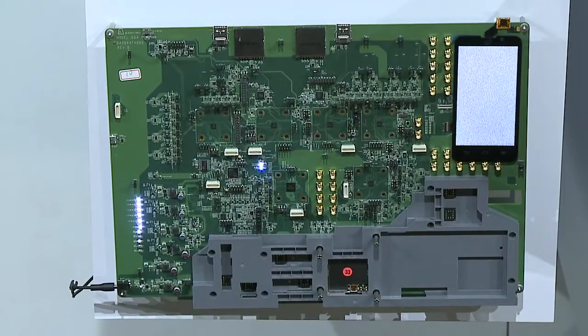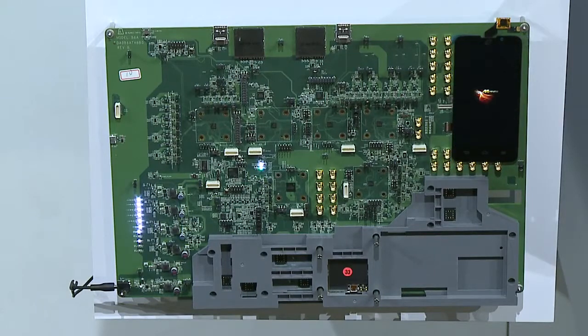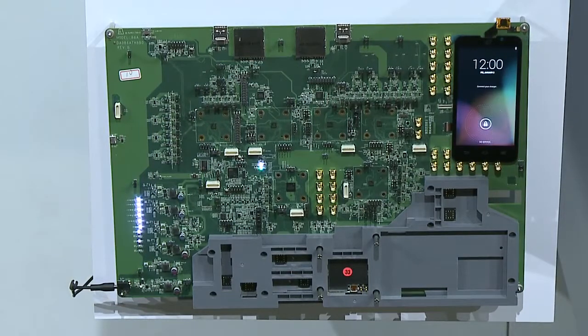So now we're booting up Android Lollipop on this board. We have the form factor AP module routing the DSI data, tunneling it through the Unipro network, and we have the Android boot logo displayed on the screen. And here it is, the lock screen for Android. At the moment, development is still gating on the firmware, so we don't have the touchscreen working yet, but we're working on that.